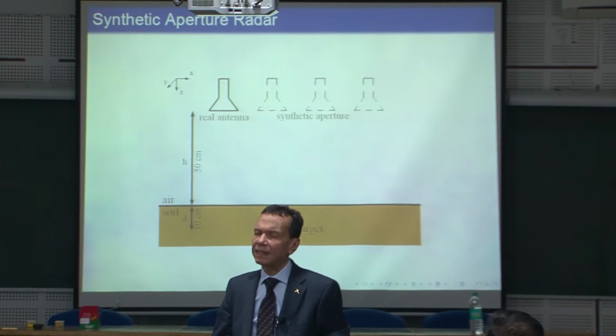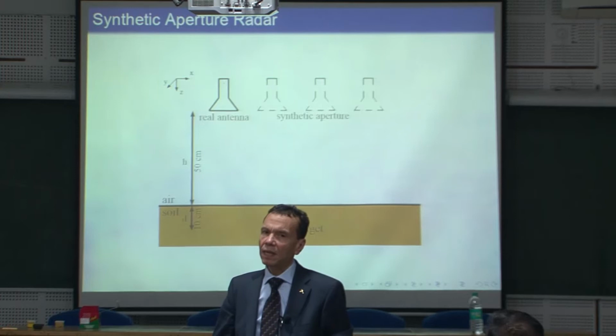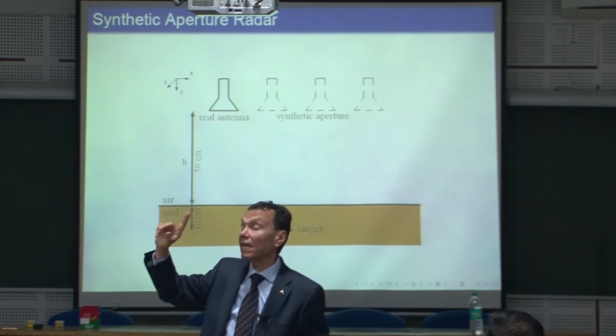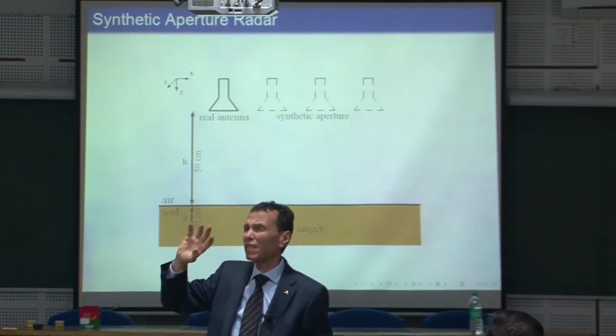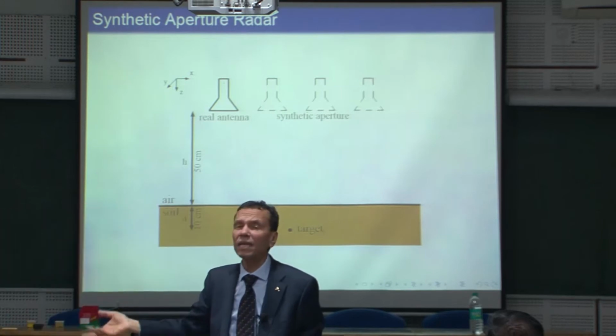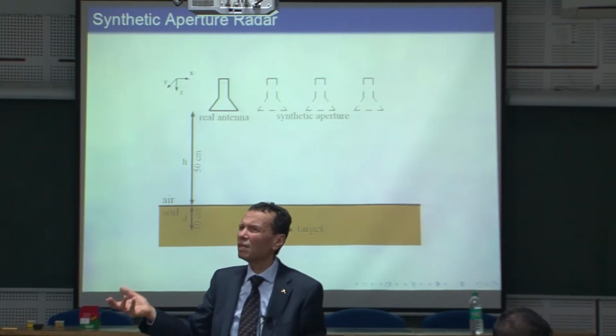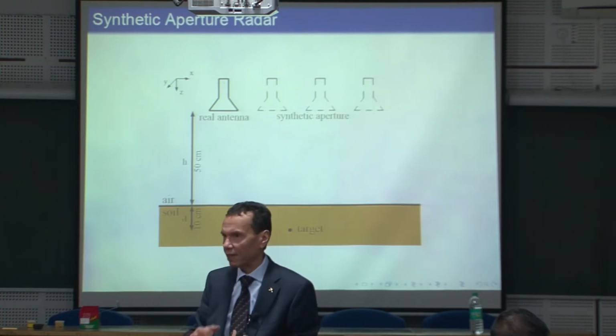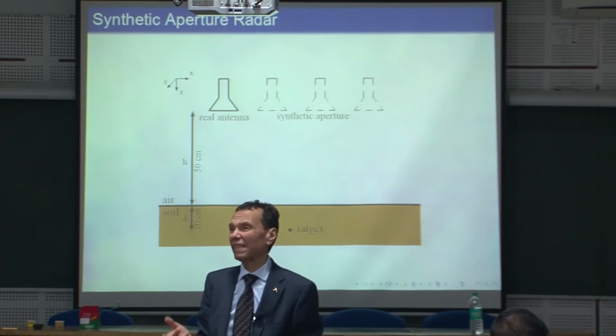I still remember that they did the calibration this way. You can put, say, a metallic plane, because you cannot have all standards in free space. This is one of the challenges in calibration in free space. You don't have through. Through maybe you can have, but open, of course, forget it. You have short and you have line.